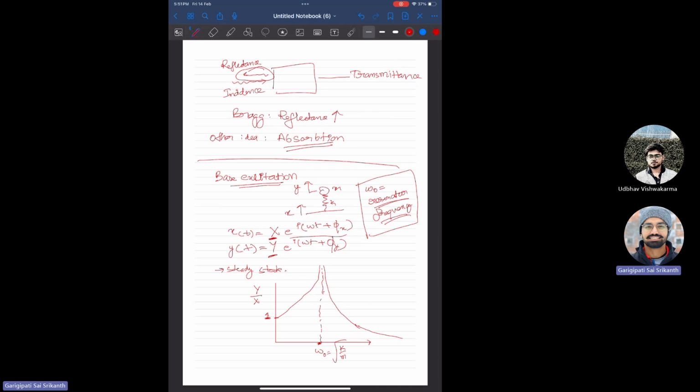When the washing machine is in the spinner mode, notice that when it starts spinning initially, the washing machine is quite stable, right? And the omegas are low. As the omega increases, the washing machine starts wobbling a lot. There's a lot of excitation.